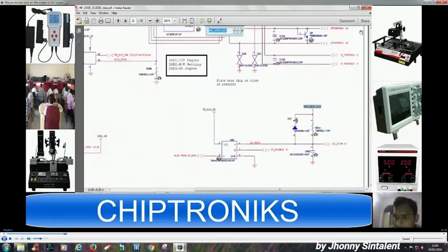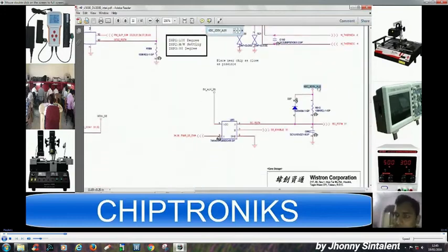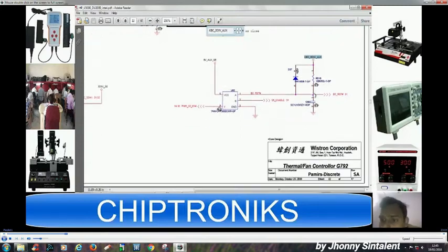Now we'll go back. So this is already there because we have already checked that this is the 3.3 LDO output of the 3 volt 5 volt regulator IC, and since we have already checked this in the previous stage, in the RTC VCC, this voltage must be there. Now this voltage is connected via this resistor and it is giving EC reset. So EC reset would also be there. If it's not there, we have to check these two components.